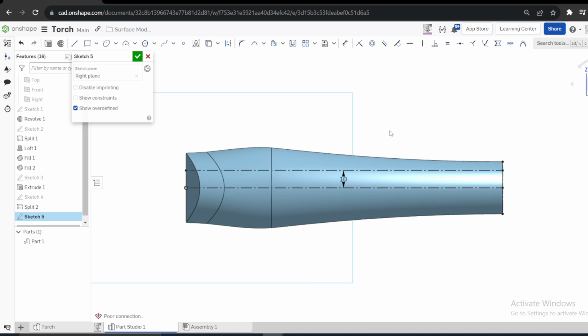Vertical like that. Then I need a spline from this line to somewhere here. Spline there. We are defining the side profile. Let me have a line at this point. Let me drop a point here, because I want the midpoint of this line, this point to touch. Then this for construction, dimension here to here to be 25.